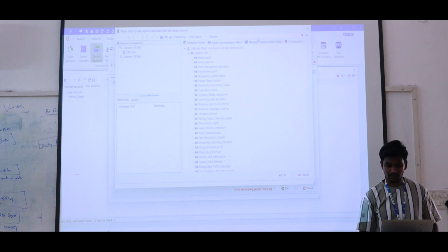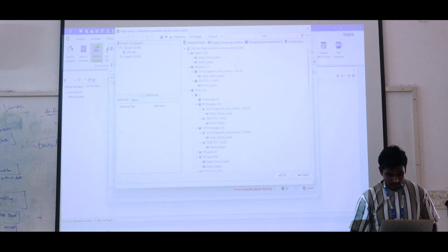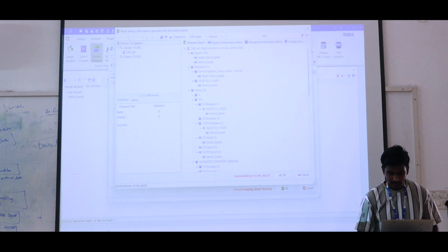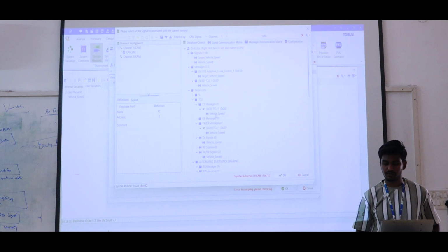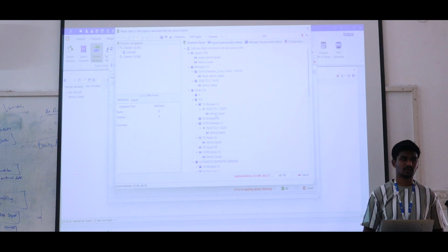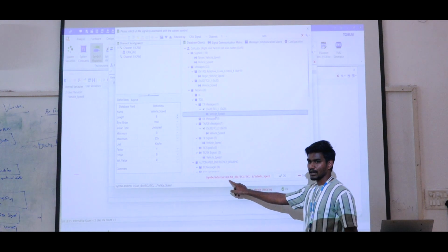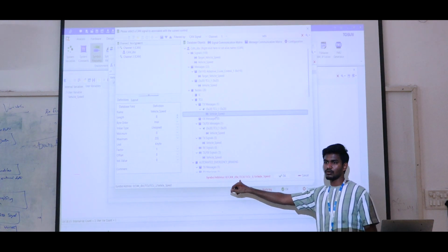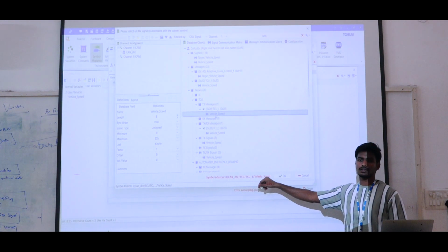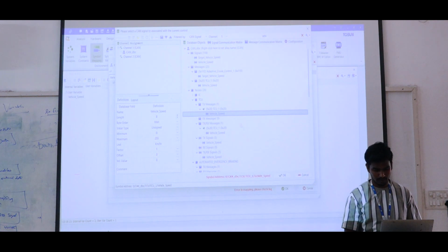Okay. So now you can type here vehicle speed. Vehicle speed you can take as the TCU vehicle speed, the transmission vehicle speed. Got it? You can select the address of CAN DVC from the TCU node, TCU message, and then check the vehicle speed and then click OK.